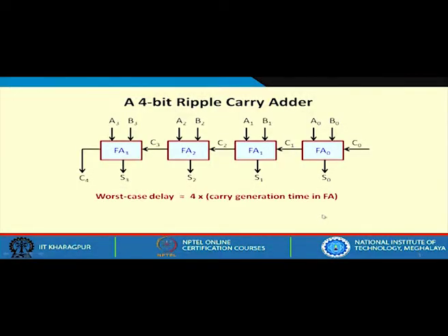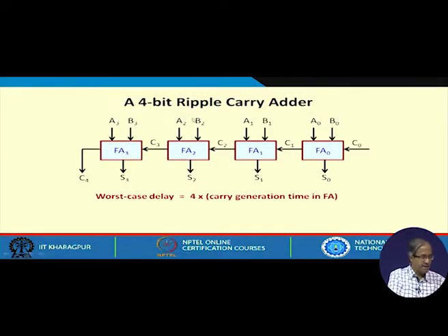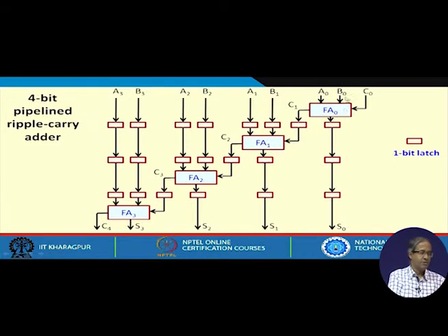So, whatever ripple carry adder was here like this, we are making it like this, we are stretching it. You just ignore these pink boxes for the time being. You see that the full adder is still a full adder, okay. But what I have done is that we have drawn it in a skewed way, and these are the 4 stages of the pipeline you are defining, and the small pink boxes will be our latches.